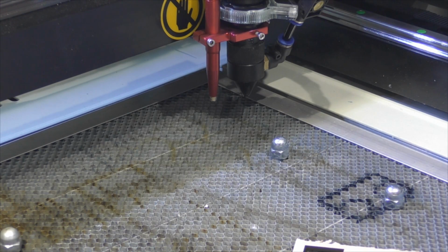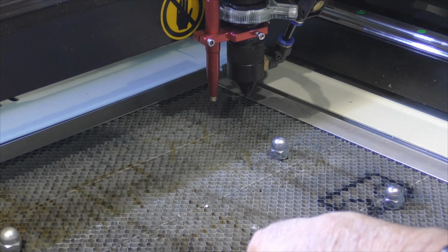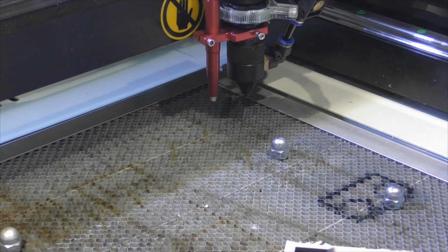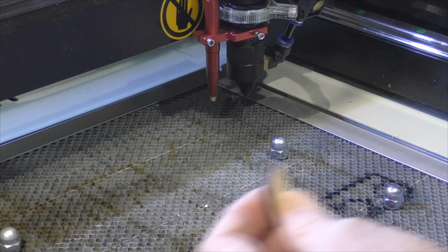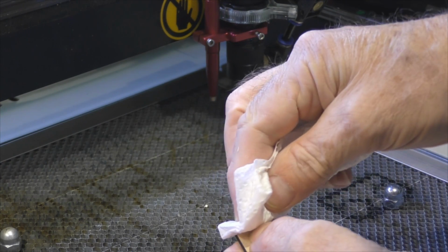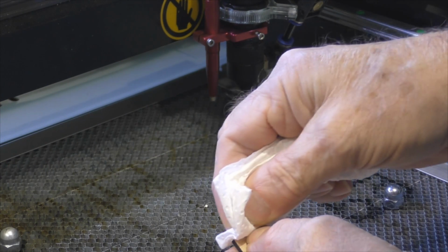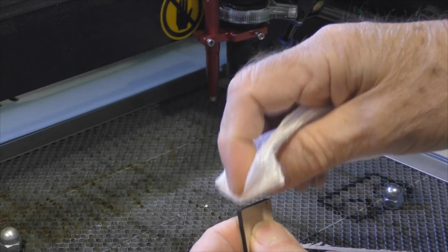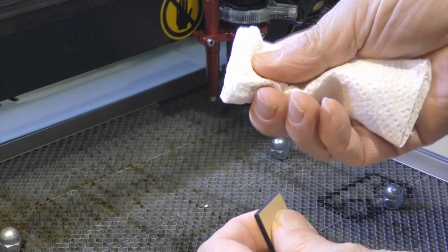Look how clean the cut is. As I mentioned to you, all organic materials burn, and burning produces smoke and charring on the edge. Now, one of the ways of knowing whether or not you've got a good cut, or you're getting close to the maximum that you can achieve, is to carry out this simple test. Get a piece of white kitchen towel and try rubbing it along the edge.